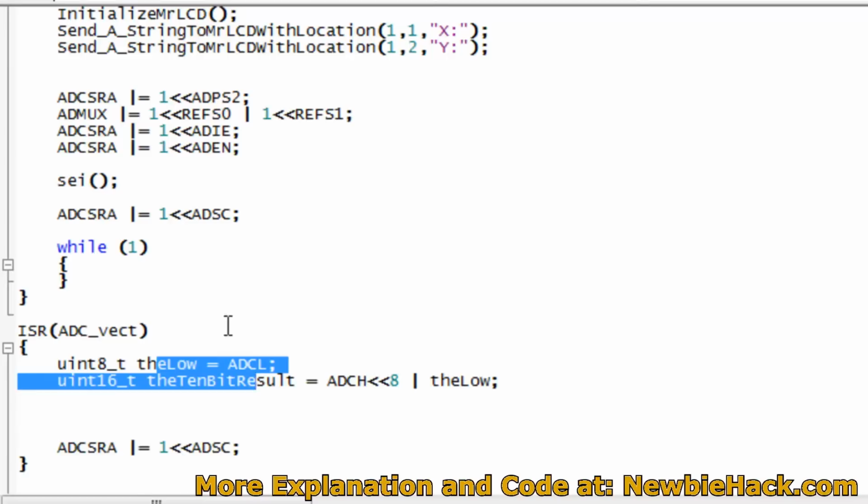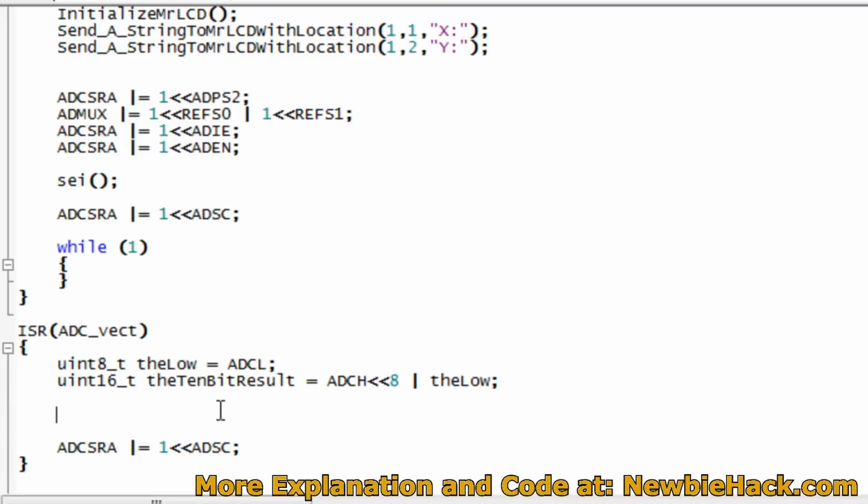It's going to channel 0 once, and then it gets the number and it'll print it out on the display, and then it'll go around again with the channel 1 and display that, go around again, channel 0, display that, go around again, channel 1, display that. And there are two different ways we can do this, or two relatively easy ways we can do the switching of channels and displaying the number on the LCD. And one way is using if and else statements, and the other way is using the switch statement.